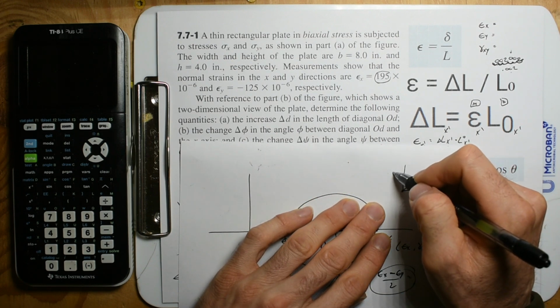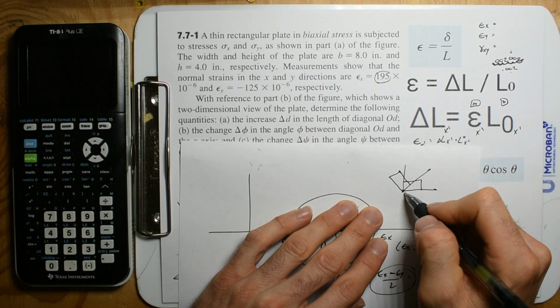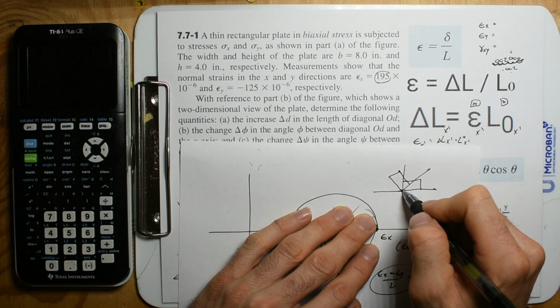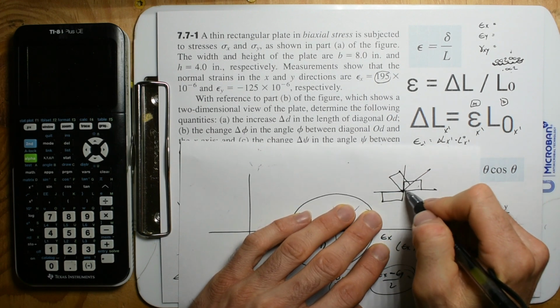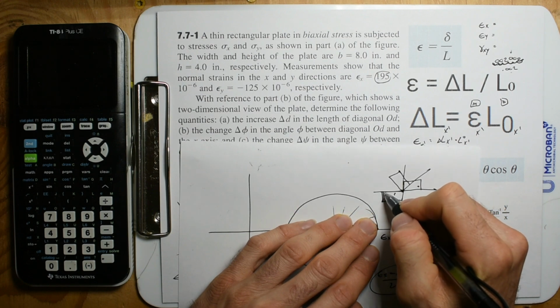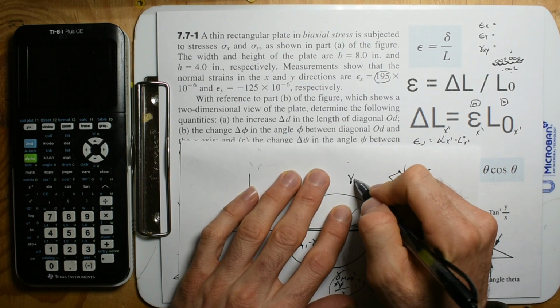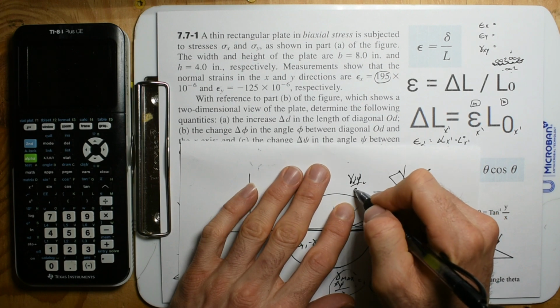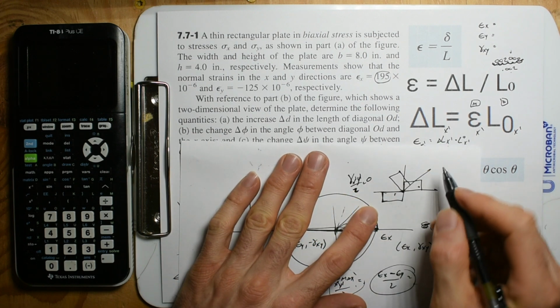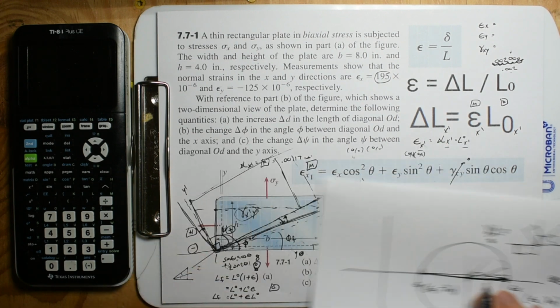We could rotate it up to there. We could also rotate it all the way down to there. So we just keep on rotating that element. When it's in this location or 180, the shear strain in the x1y1, that value divided by 2, or just that value, is 0. But in every other orientation, it's not.